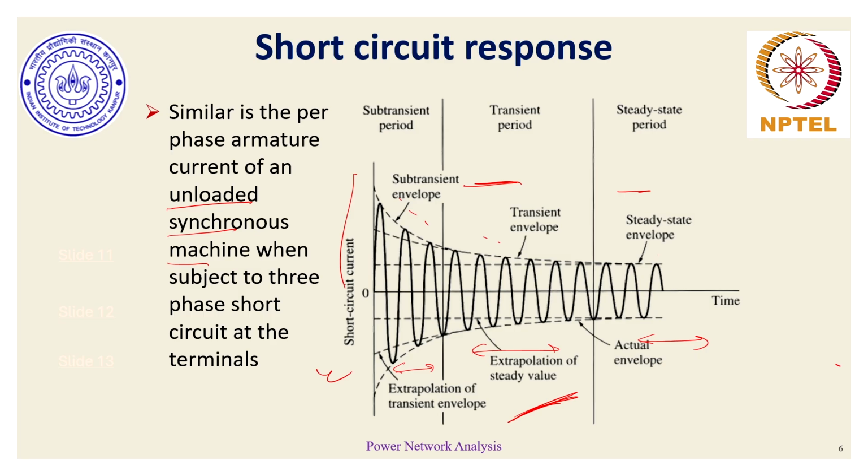What we have not understood from the devil's advocate perspective is that instead of this envelope going down, isn't there a possibility that this envelope might go up? In stability analysis, we will try to find those conditions or situations where this envelope will tend to go up, specifically from the fault current perspective. And that is where the transient period study would come in, because essentially if the envelope would go up, it would more or less start with a similar subtransient period where the current either has its peak in the subtransient for fault or has its minimum during the stability analysis for unstable conditions.